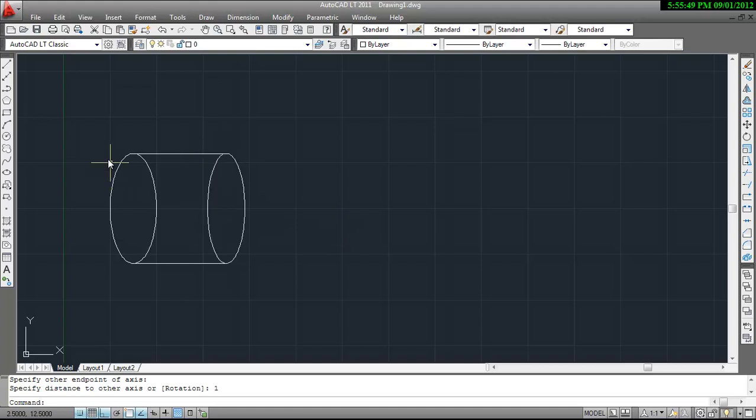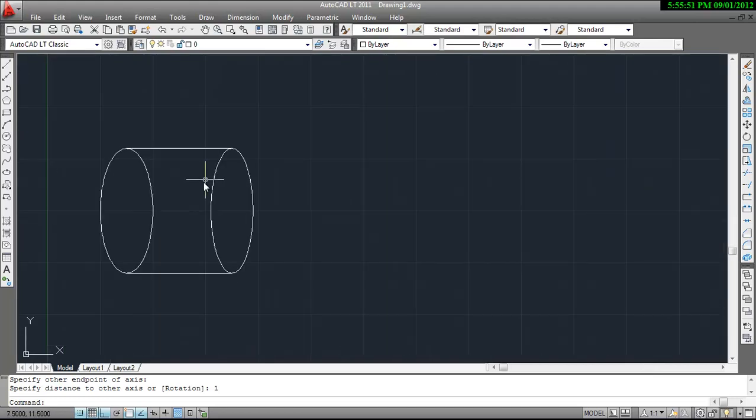Now, as you can see, this is a cylinder, but if you want this part to be removed, because it is a cylinder, so this part should not be shown. This one, I can remove that. For doing that, you have to write trim in the command box, T R I M, trim, give an enter. It will ask you about the object you want to trim. Select all, every object.